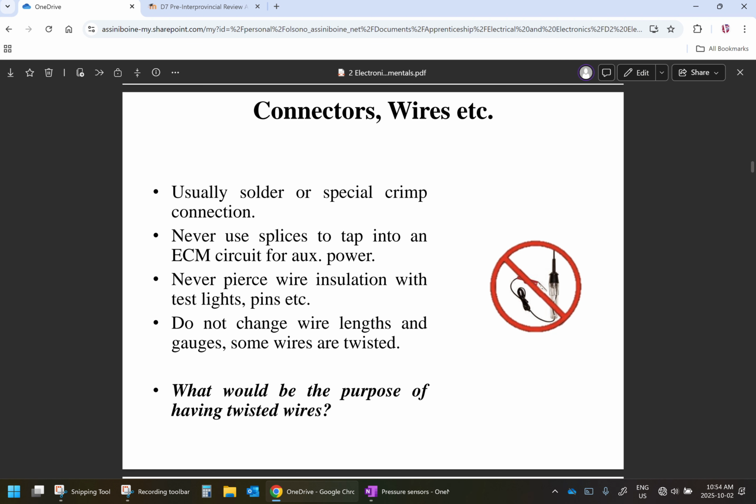Believe it or not, some manufacturers are going back to butt connectors. Others will recommend just replacing the broken section of wire in the harness, repinning and putting a new conductor in. That's one way. We don't want to pierce insulation because that's a good way to get corrosion and then resistances and stuff.